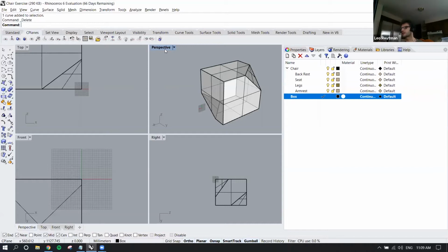So we always choose a dot in 2D space. And basically that's how you choose this 2D space in the 3D world of Rhino. Basically, the construction plane is the plane where we're choosing dots. So you choose a plane surface which is your working surface for a particular time when you are working with your model.